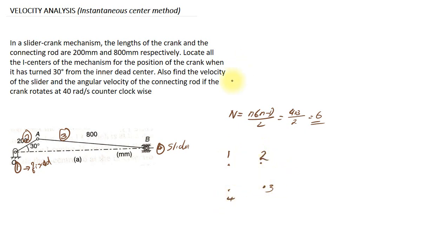The fixed and permanent instantaneous centers are 1, 2; 2, 3; 3, 4; and 4, 1. That is, I12, I23, I34 and I41. Next are the ones that are neither fixed nor permanent, that is 1, 3 and 2, 4. So I13 and I24. These are all the 6 instantaneous centers of our question.